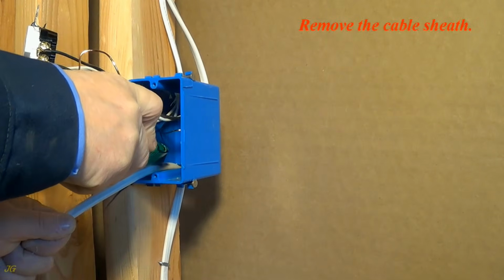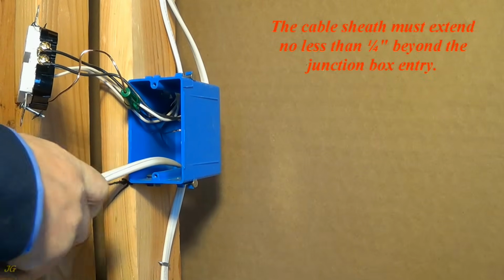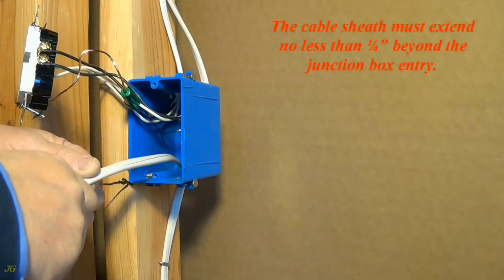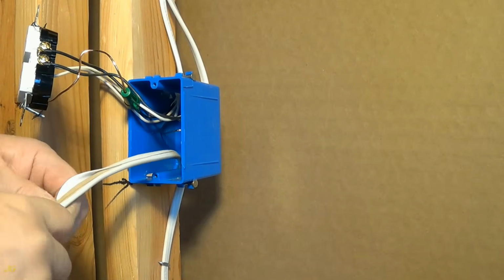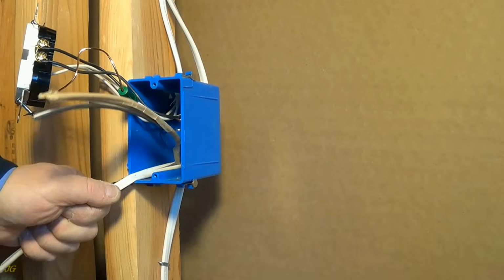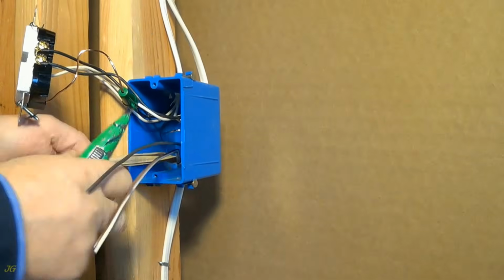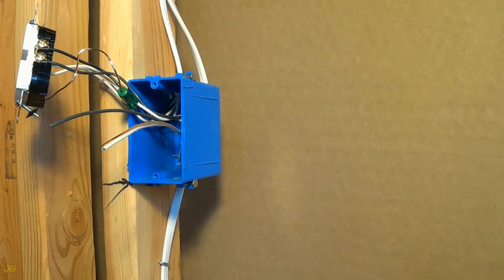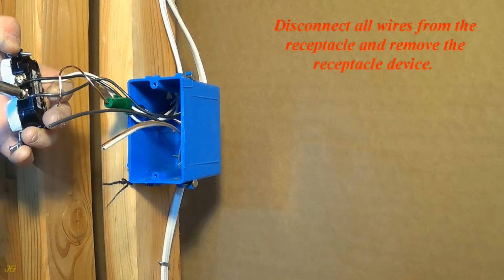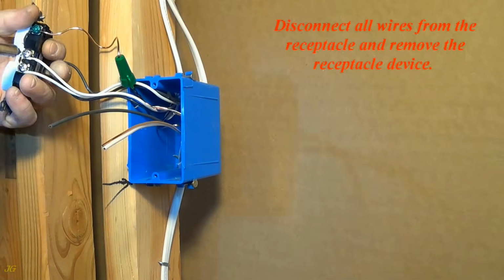Remove the cable sheath. The cable sheath must extend no less than 1/4 inch beyond the junction box entry. Disconnect all wires from the receptacle and remove the receptacle device.